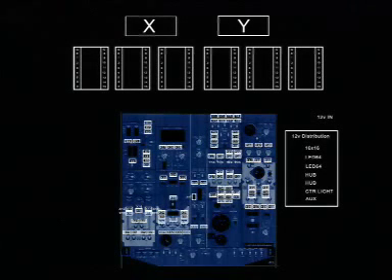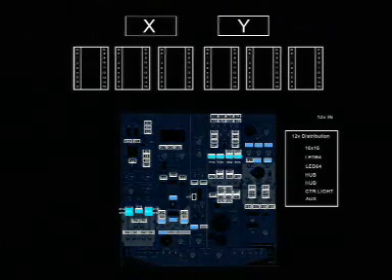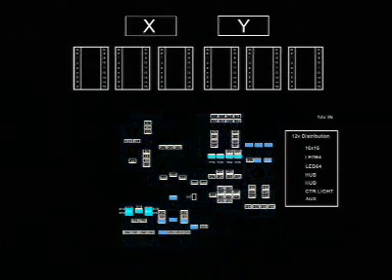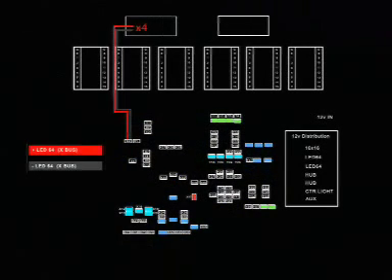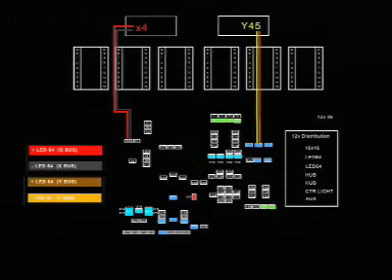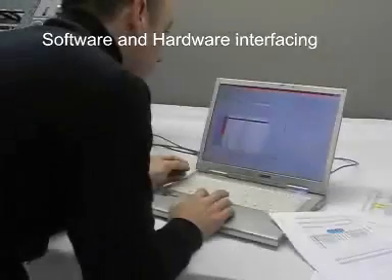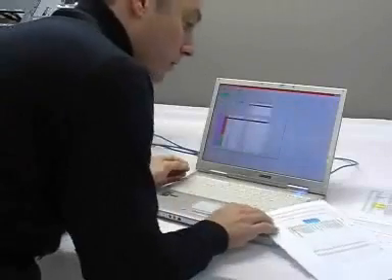Annunciator colours were defined. Single blue required only one output, dual state valve lights required 2 outputs to give the dim and bright states of the 737 valve positions. Again, colour coding was used to track the outputs of each card. The next step is setting each input and output so it can communicate directly with PM Systems.